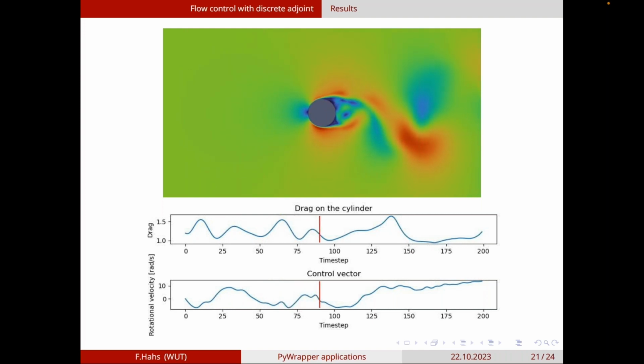No, it does not. What I've noticed is that the mechanism of drag reduction has to do with increasing the period of the vortex shedding. So as the drag falls, the vortices get shed less and less, and because of this, I haven't noticed much of a correlation. Although, like I said, this is for a Reynolds number which was too high. Now I'm calculating one with a lower Reynolds number, and there is some more similarity.